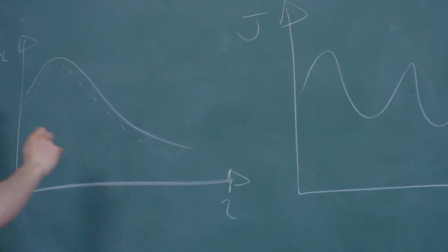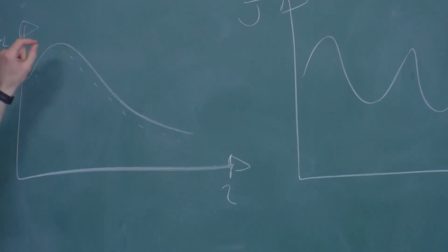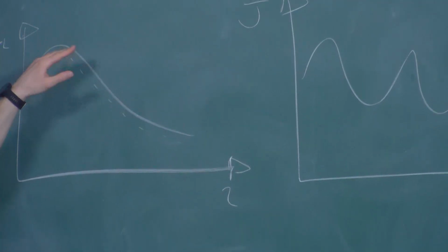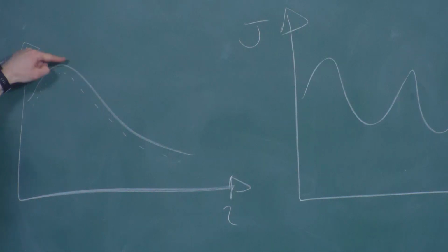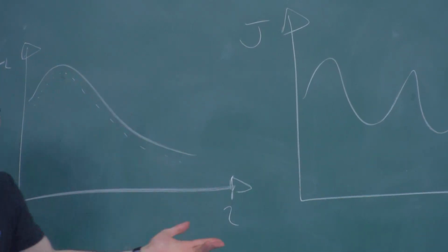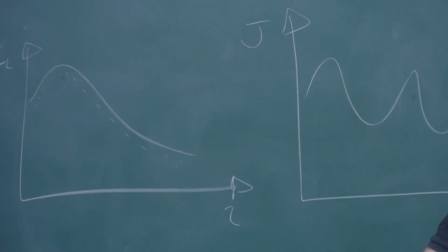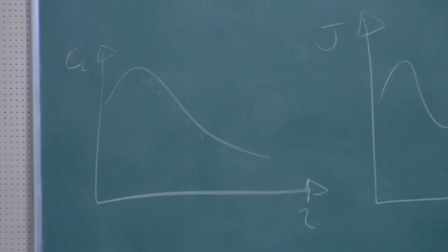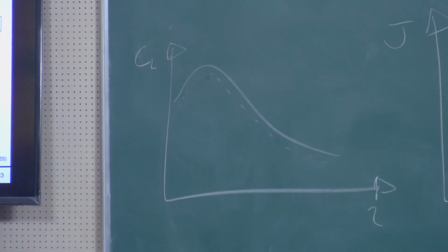But they looked at a ferritic material, and in that ferritic material, in minutes, you have a hydrogen concentration that was already 90% of the steady state value. So yes, you can add carbides, and that will delay how quickly you get to this point, but in minutes you're already here. So from an engineering point of view, people said, okay, this is not going to work. This is the idea. If you have a permanent source of hydrogen, you'll get to steady state or close to steady state very, very quickly. And I think what they did was fine. I mean, there's nothing wrong with it.